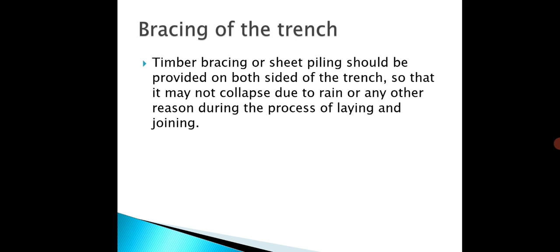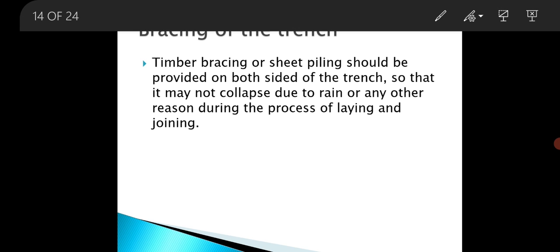Then the next step is bracing of the trench. After the excavation, the trench is provided with timber bracing or sheet piling so that it may not collapse due to rain or any other reason during the process of laying and joining.